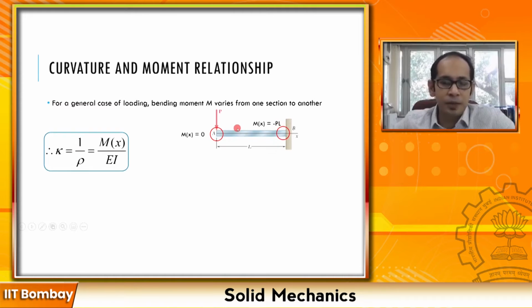Anyway, the fact of the matter is, here you have a 0 bending moment, so that should automatically tell you that, since curvature is related to the moment, your curvature must be equal to 0, and your radius of curvature, which is the inverse of the curvature, must be infinite, right? As opposed to that, at this place, because of the maximum bending moment in the beam, you will have a maximum curvature, and correspondingly a value of your radius of curvature rho.